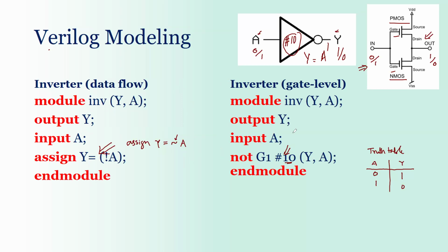And after compiling the code, you can verify the design through simulation by writing a test bench, which is basically another set of code that applies stimulus to your circuit. For example, the stimulus to this circuit is logic 0 or 1 as an input, and accordingly you monitor the output.